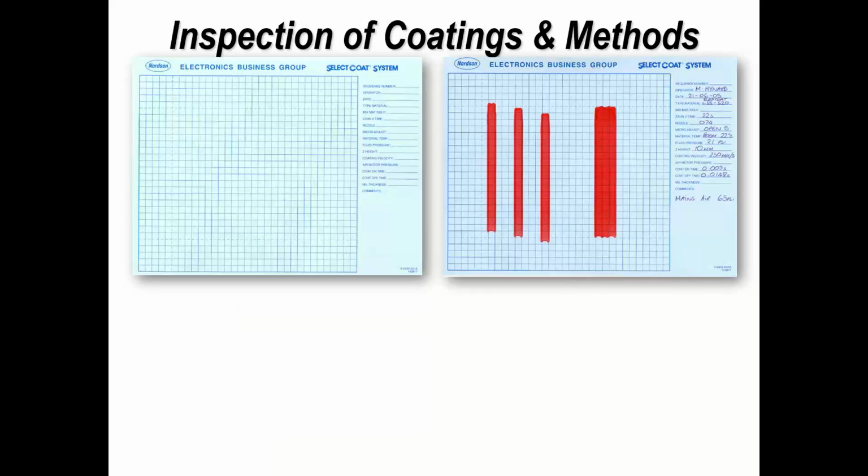I mentioned about spraying onto boards or spraying onto test cards, and this is a test card that Nordson have used traditionally to demonstrate successful setup of a machine and all the other parameters like nozzles, etc., and record the information. So what you can see here are parallel lines. You can see that you've got thin lines and wide lines. So basically you would repeat a pattern and do that at the start of a shift. You might do it at the start of each shift, or you might do it after calibration, changing materials, changing parameters. So you've got something as a point of reference.